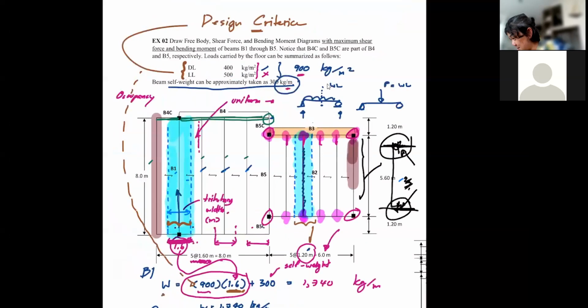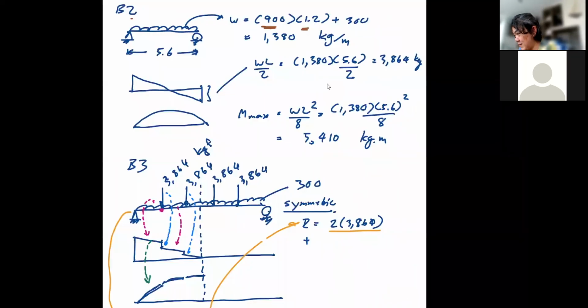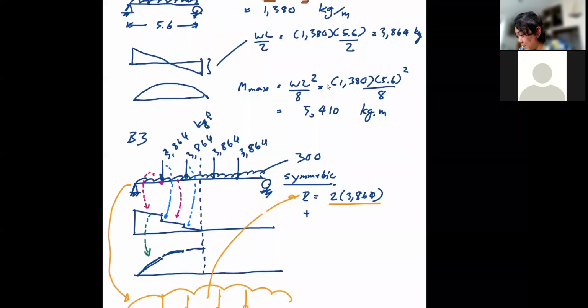Coming in from this case, the beam is 6 meters long, right? So that means the reaction due to the uniform load would be 3 meters multiplied by 300. Right? You guys following me?